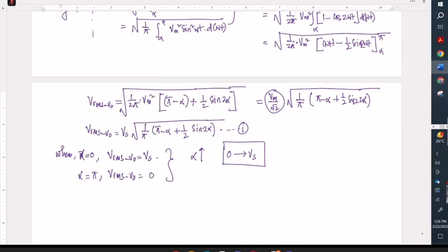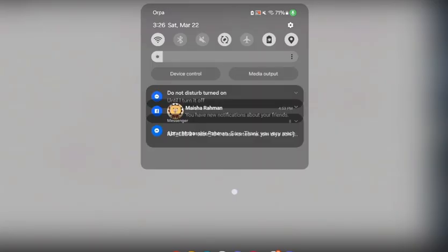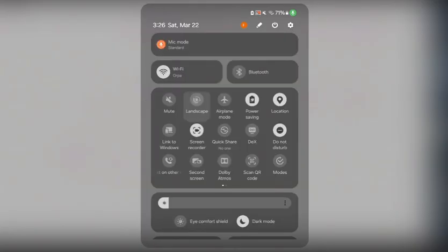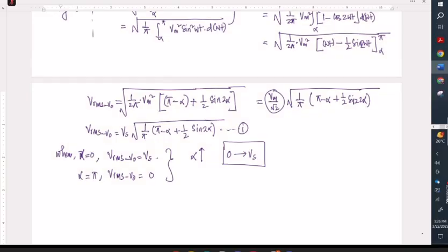So now, this is the very basic type of AC to AC controller circuit, but this circuit has some limitations. For example, if you remember my thyristor circuit, this is my anode, this is my cathode, so this is positive, this is negative, and then we have to put a gate signal. The gate signal should be between cathode and gate, plus and minus, so you have to put a positive signal between cathode and gate to turn this thyristor on.